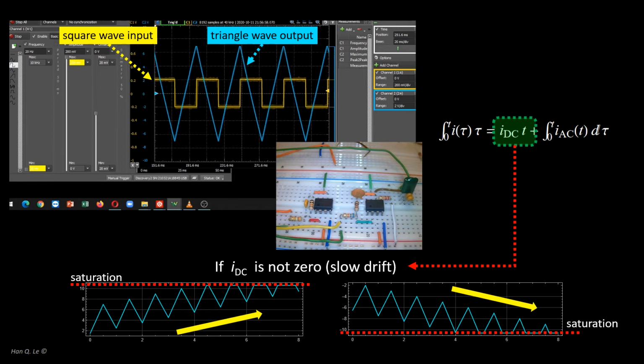In principle, with zero offset, the AD2 waveGen signal output should have zero DC component. However, random drifts on the millivolt or sub-millivolt level may occur, and although that can be controlled with a small offset, even slow drift can be a nuisance for data acquisition. The problem is random in nature, and reports from users in the past varied. Some AD2 were stable, some were not. The following are some approaches to solve the problem.